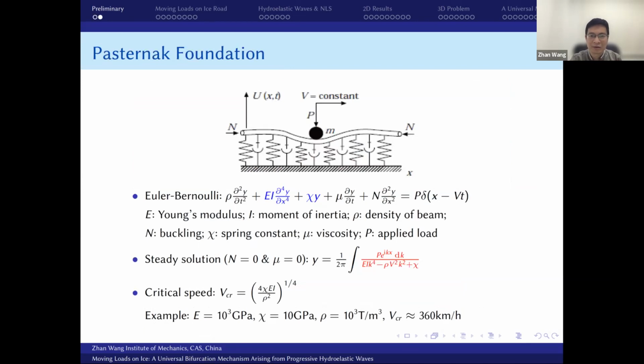So we can then formulate the problem using mathematics, writing it using physical laws. It's just Newton's second law, F equals ma, using the Euler-Bernoulli beam. So ma is the first term, the second derivative with respect to time, and you have two restoring forces. The first restoring force: you can imagine that the beam is an elastic beam, and you can have a deformation, elastic bending.